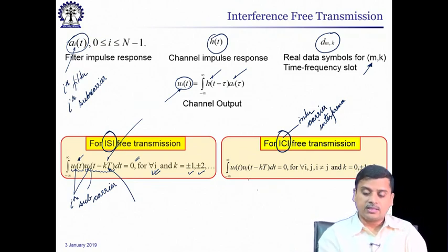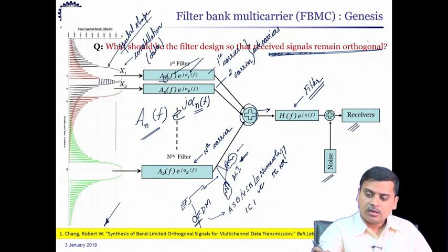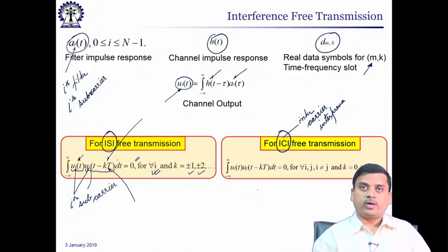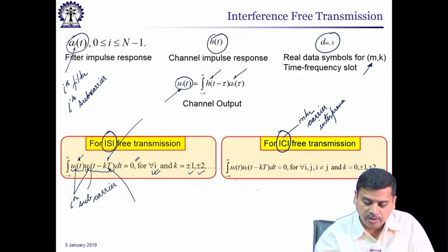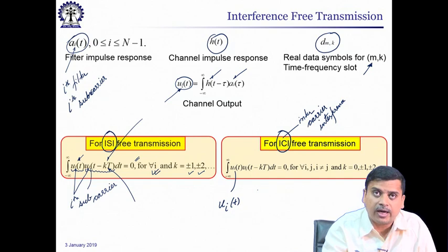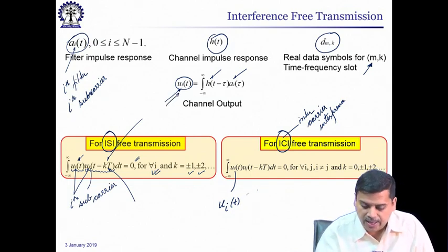So, here when we translate these requirements of having orthogonality, we have already translated one in the time domain. If we look at the frequency domain, we find we have used over here ui(t), that is the output from the ith channel, and uj, which is the neighboring or any other value of the subcarrier index, (t minus kT).